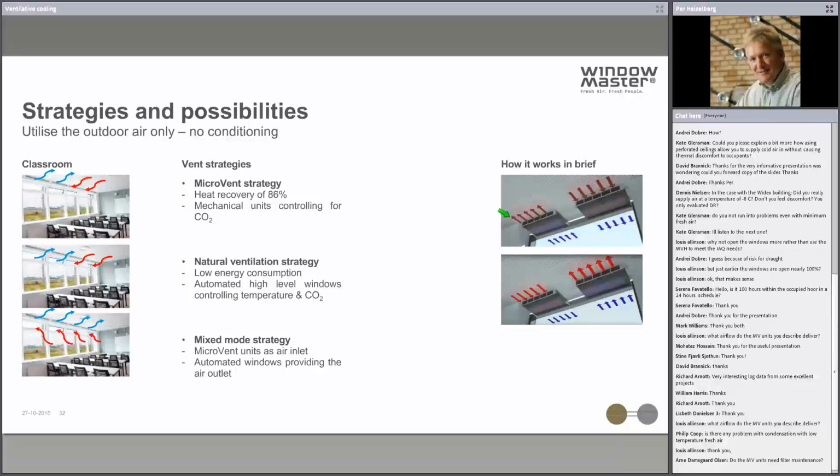This unit will bring in air and the other one will exhaust the air. Then the next moment, one or two minutes later, depending on the conditions inside, this unit will be the exhaust unit and this one will be the inlet unit instead. Condensation will occur to some extent, but we have a slope on the unit which lets the water run out of it.